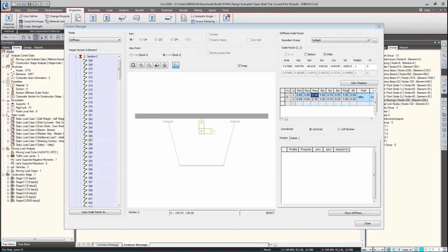One thing you should understand about the software is that anything that is horizontal, the software will directly consider as a beam. Anything that is vertical, it considers as a column, and anything that is slanted, it considers as bracing. By default, the software will automatically take these into consideration when designing. But if you wish to design a column as a beam, then you have to modify the section type. That's the only thing that you have to do.